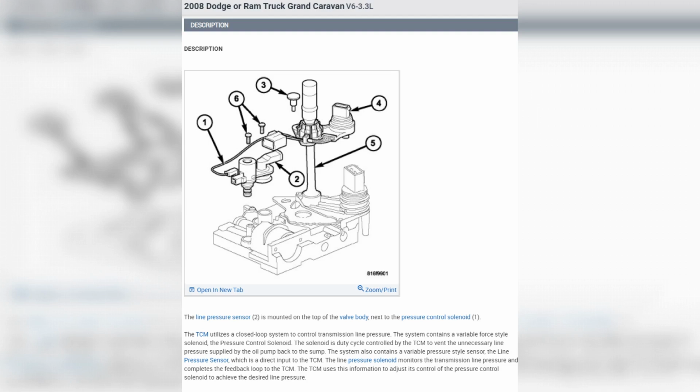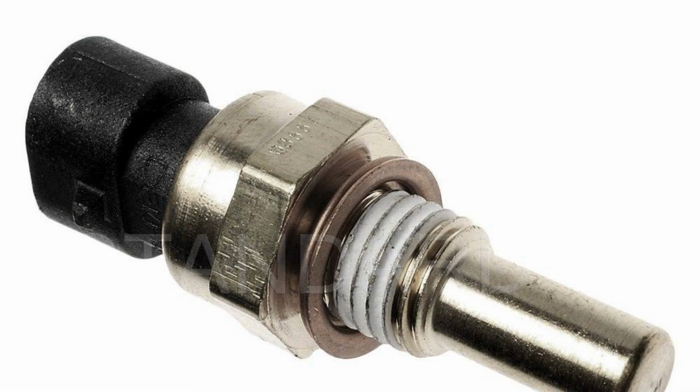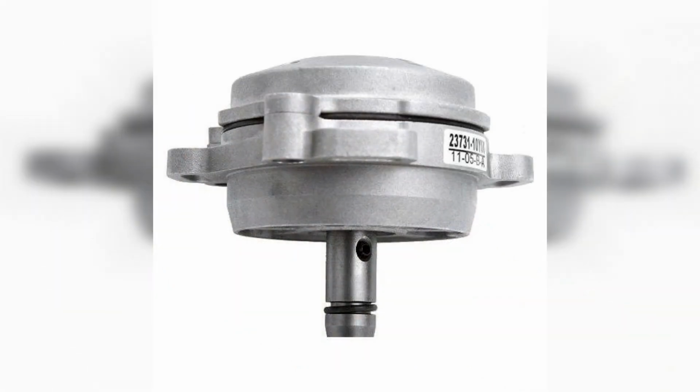What causes the P0870 code? There are several reasons why P0870 may occur: low transmission fluid, a high pressure pump with a faulty transmission, a defective transmission, also known as a slipping transmission, a faulty temperature sensor, engine overheating, or a faulty or defective PCM.